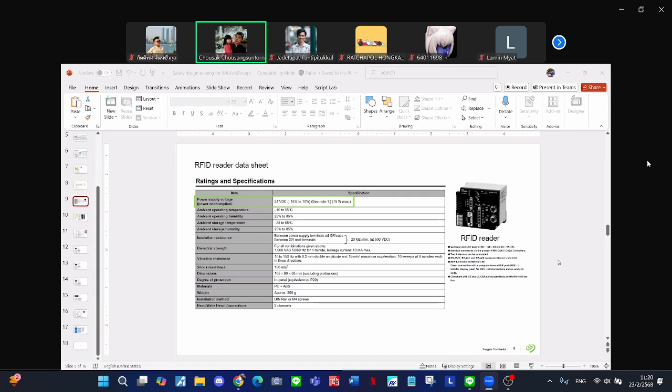The closest standard value is 10 as well. Okay. We will use 10 ampere to calculate back to the wire size. Go to the table. The maximum at 10 should be this cable. The wire size is supposed to be 16 AWG. Yeah, that's it for the DC side. Any questions so far?